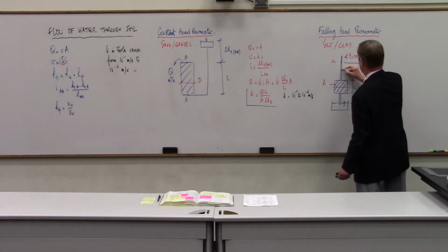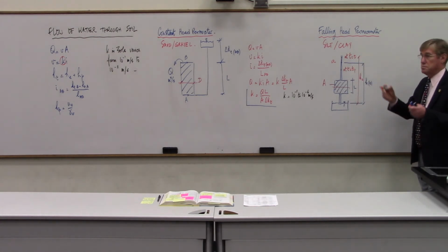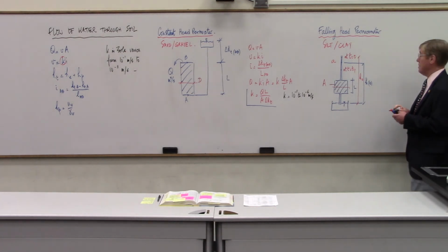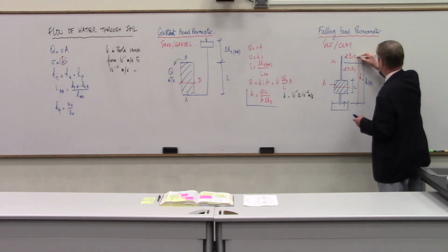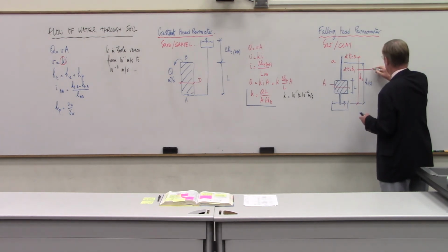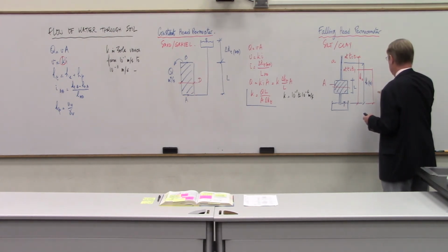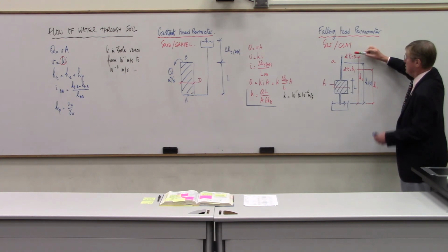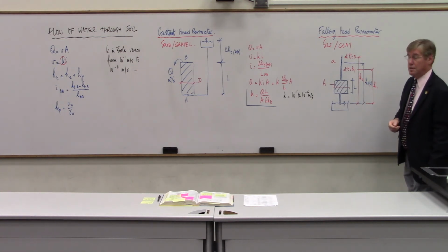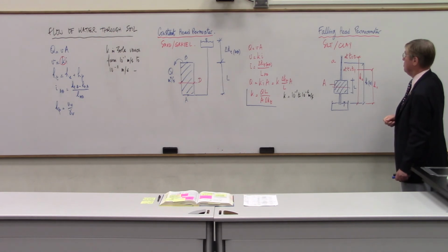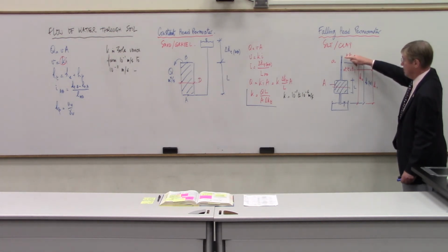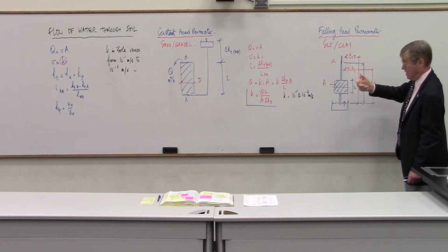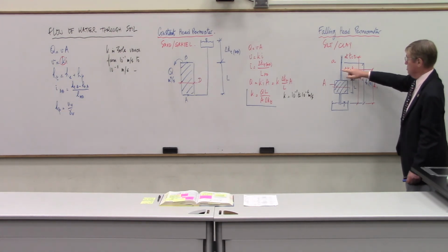And then at t equals t sub 1, let's say, 10 minutes. Then at this point, we're going to have a lower value, and we're going to call that H1. So during the test, you have the time watch. You start the time, and you record that height, and the water goes down, goes down, goes down. 10 minutes later, click, you record T1, and you record this level.